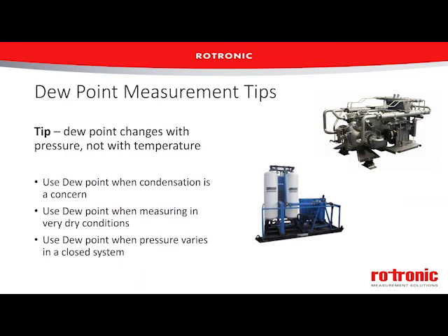So a few things for us to understand about our dew point or frost point measurements. They are pressure dependent. So as the pressure of a system changes, we have to understand that that will affect our dew point or frost point temperatures. They are not dependent on temperature. So if we've got temperature gradients in a space, those are not going to affect the dew point or frost point temperatures. We absolutely, though, need to be careful if we're dealing with systems where the pressure changes. Dew point is quite often used in compressed air systems, and then we are definitely talking about pressure changes, so we have to be careful with that.